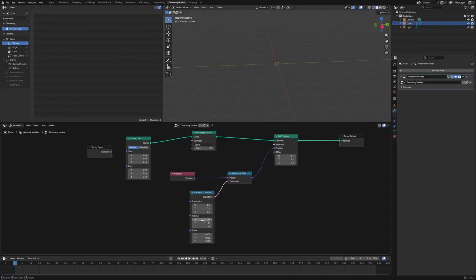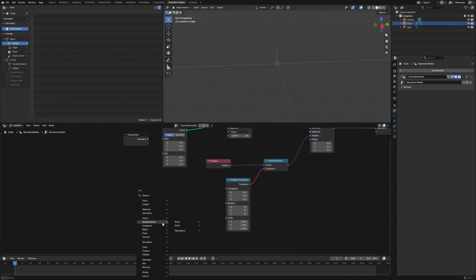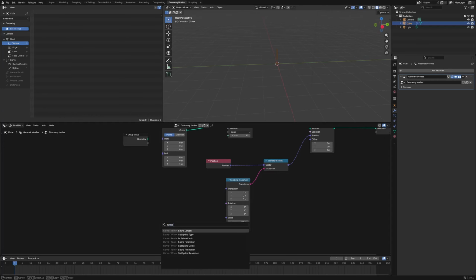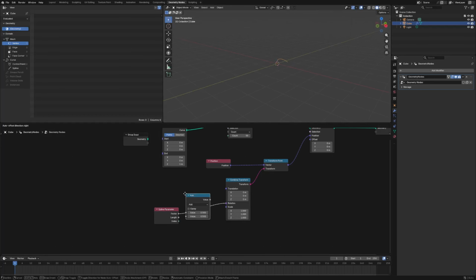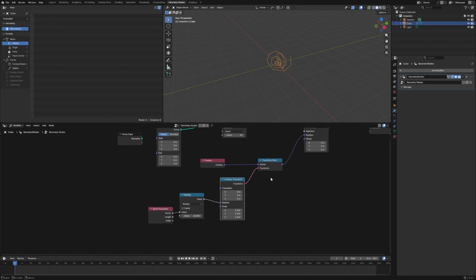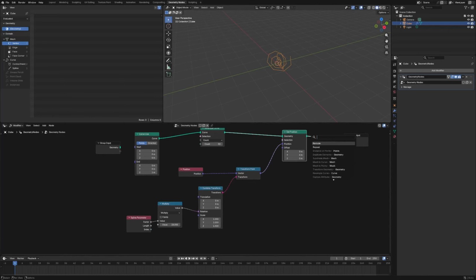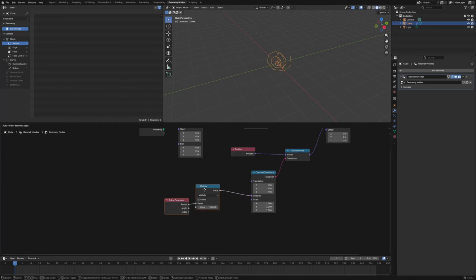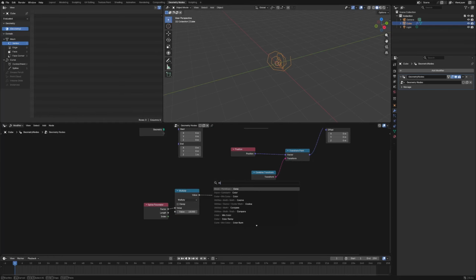And how do we want to drive that motion? Really simply, we want to drive it with a spline parameter. I'll put a factor in just so you guys can see it. We did a math node right here and multiplied it, and we get this cool spiraling effect. Why is it happening? Because it's going across the XYZ of the rotation as well. So we can clamp that really hard using a combine XYZ and put it just on the X. Now we have this nice curve, flippy floppy thing.